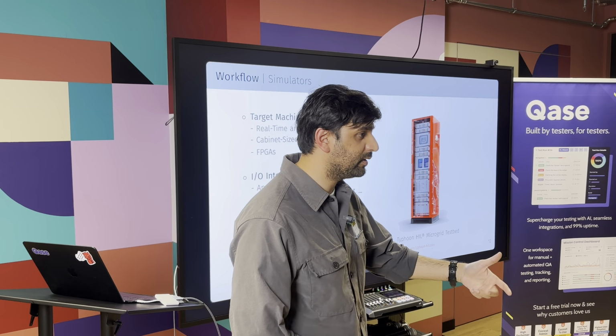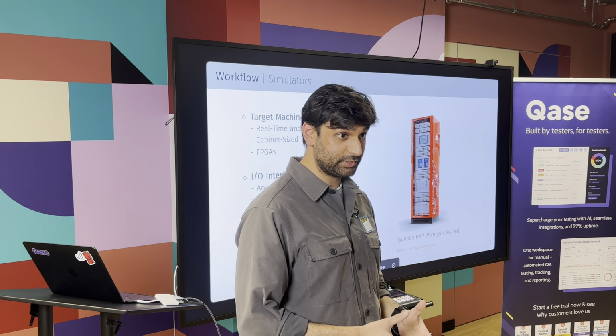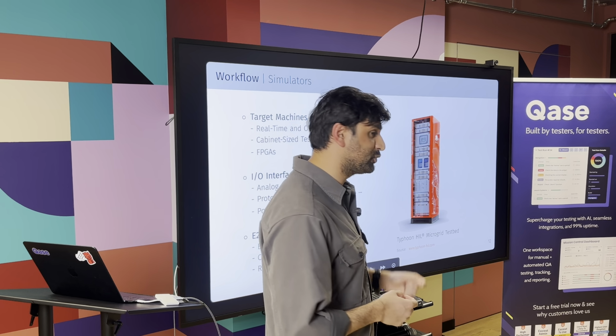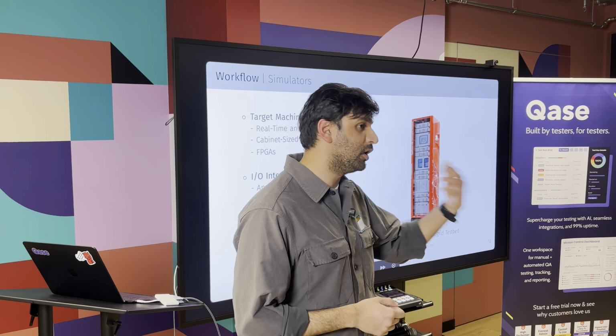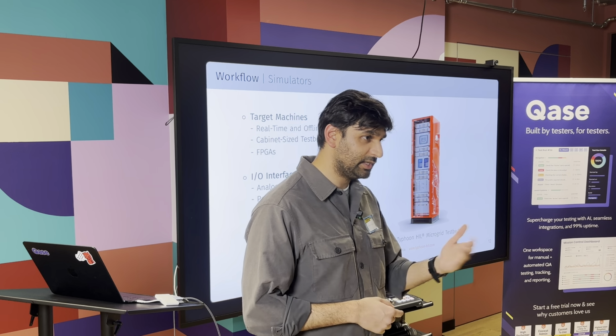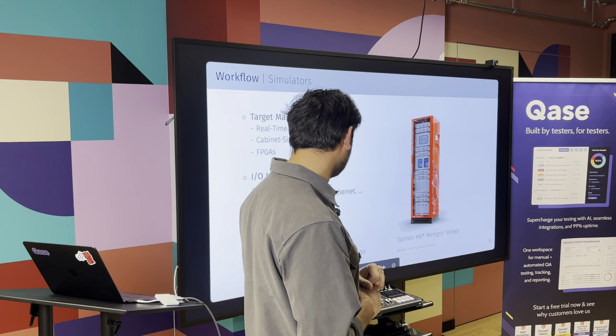So you might be okay for testing, but you might want to test real power grids, like real scenarios. So you can connect this up to a power amplifier and you can go up to megawatts and so forth. And you can really test things like fault cases, electrical failures and blackouts and whatnot. So you can go one step further.